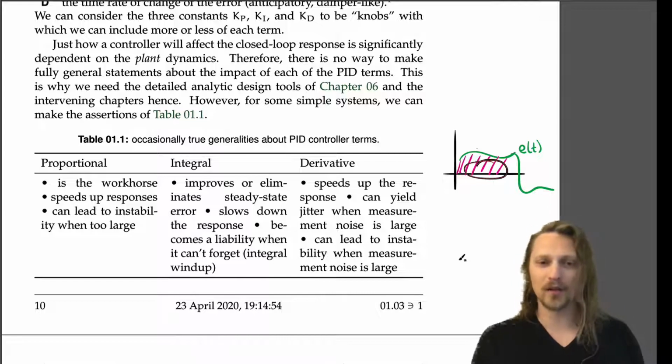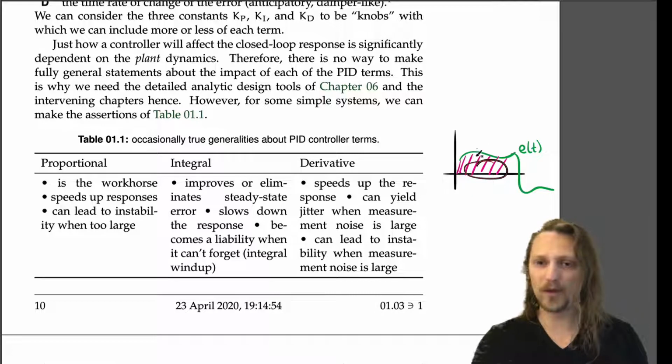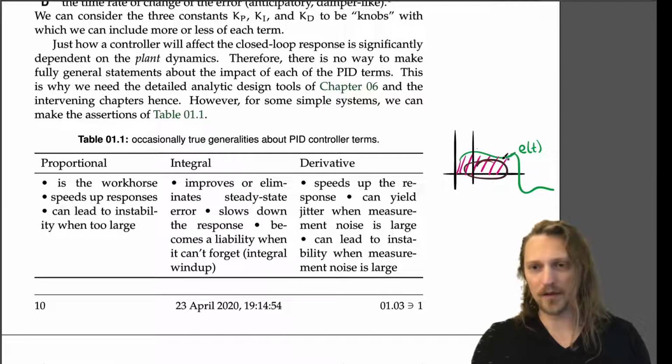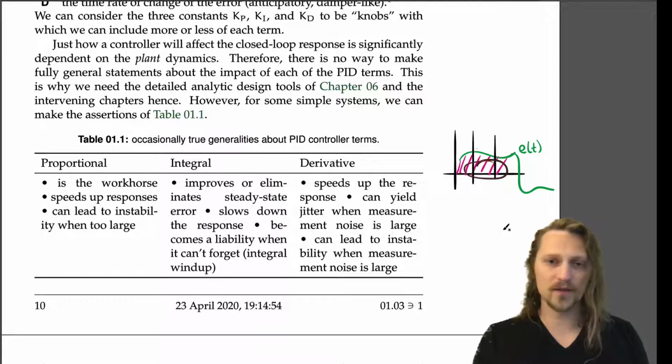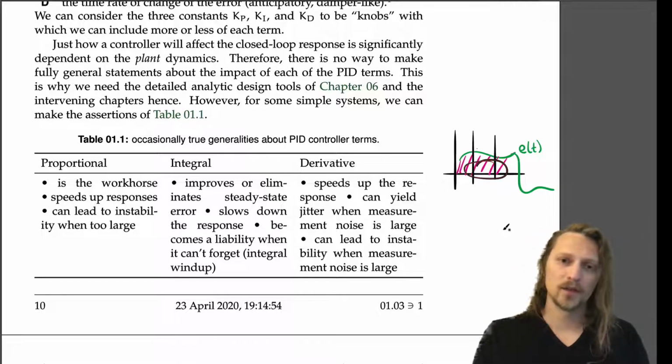So we have ways of dealing with that by taking a window instead of taking the integral from 0 to the current time. We can take a window, and that can mitigate some of those integral windup effects. So it's one of the several nuances of PID control, dealing with integral windup.